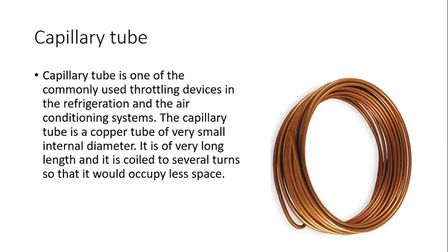Capillary tubes. This is one type of metering device, the other two being the more common TXV, which is a thermal expansion valve, and the piston or fixed orifice metering device. These are very small tubes that take a little bit of Freon through a pipe, which will cause it to expand just like the other items do. You'll see some capillary tubes in the future, but they're not used as much in the industry as a metering device. It's the TXV.